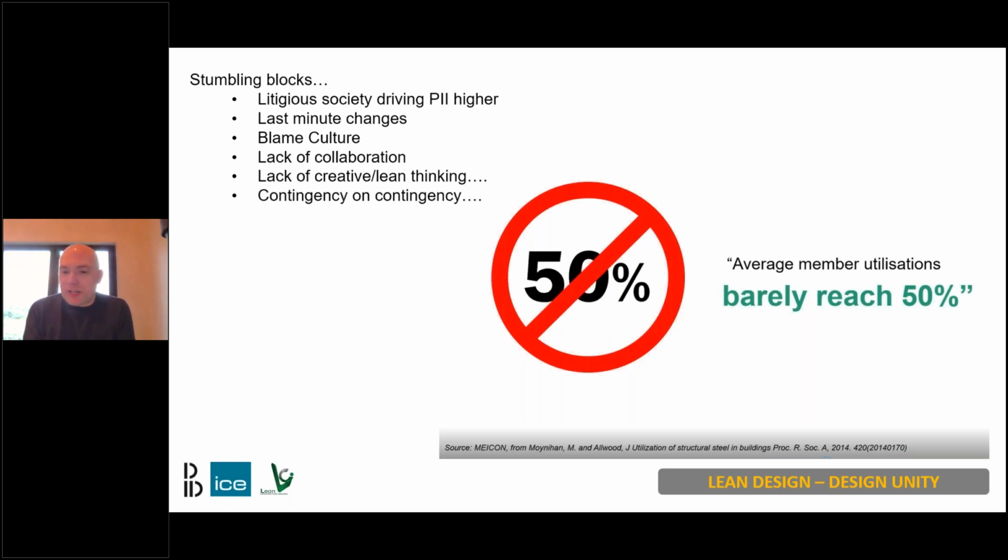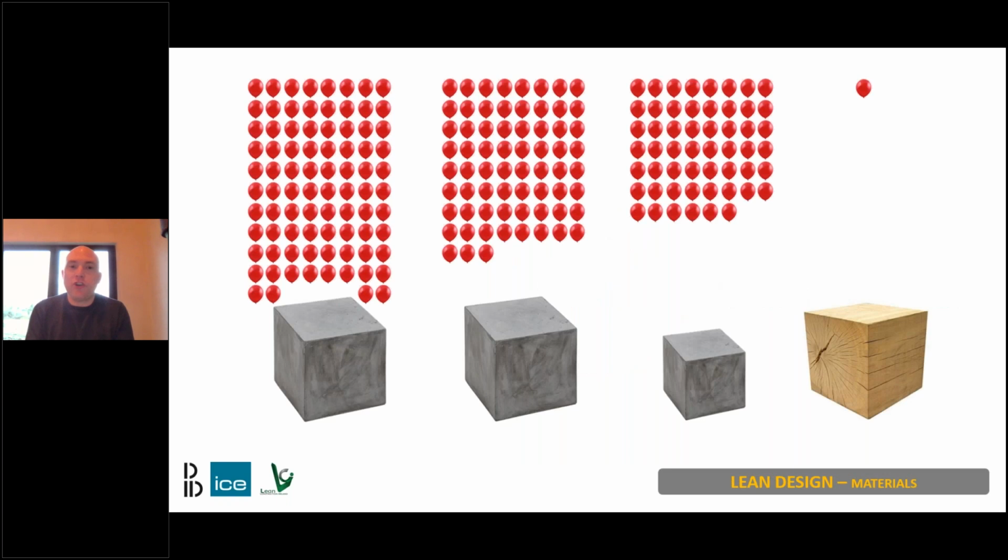So trying to show diagrammatically what that means, well, that cube of concrete there represents a 150 mil concrete cube of normal OPC cement concrete, and those party balloons there represent a magnitude of CO2 emissions associated with that. If we then look at the same cube of concrete and we look at things like cement replacement, so 50% GGBFS, or actually looking at making reductions in those very carbon hungry concrete components, then there's another reduction in the amount of CO2.